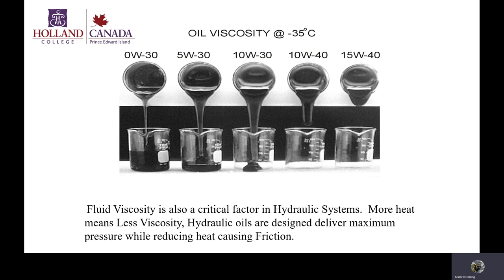As a result of that, we've had systems where we just leave them running 24 hours a day, because if you shut them off, especially when you get heavier oils, heavier gear oils, lubricant oils, and large machinery, they will literally turn into this basically syrupy goo, and you won't be able to start them again, because it's like the crankshaft of the motor or the compressor is sitting in tar. It's not moving anywhere, and if you try to start it, you'll just break it.